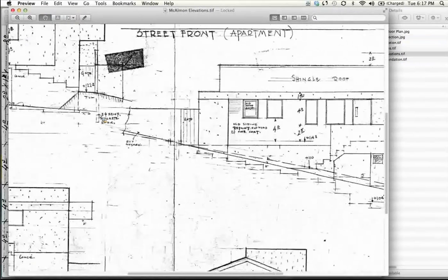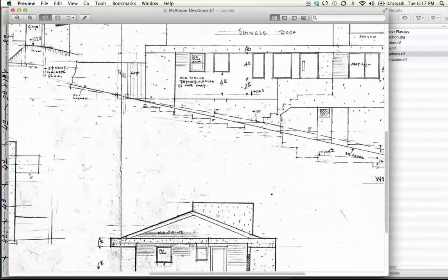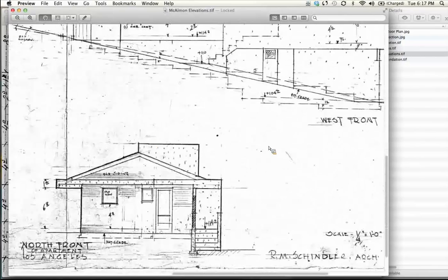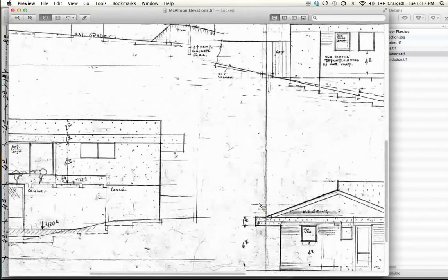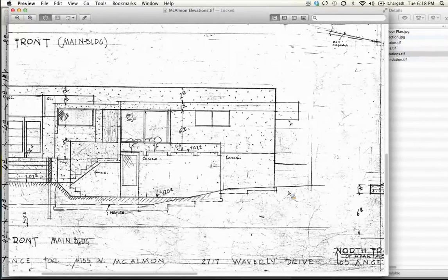And why do we do that? It's really just because it's much easier to place the concrete that way, as a series of little discrete step segments, as opposed to trying to follow the smooth foundation down. Actually, there you get a pretty good sense of it, where he keeps on doing it in segments and jumping up either 1 foot or 2 foot, but he keeps on jumping up a little bit.